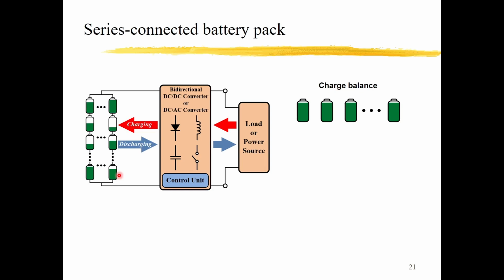Or if your charging protection or discharging protection function does not work well, then overcharge or over discharge may damage the system. That is also not favored. Both cases are not favored here, limiting the capacity or damaging the battery. They are bad for our system. So we have to make the cells balanced to prevent these issues.